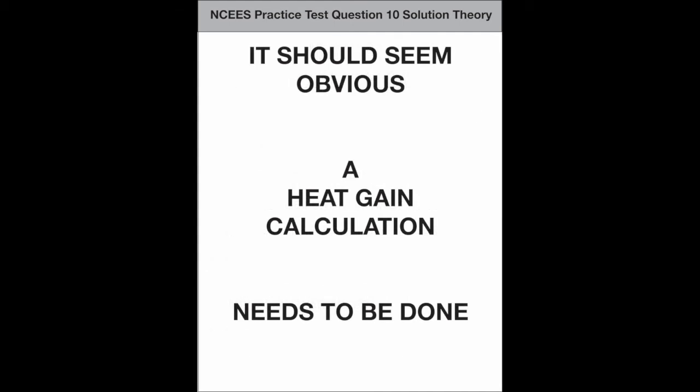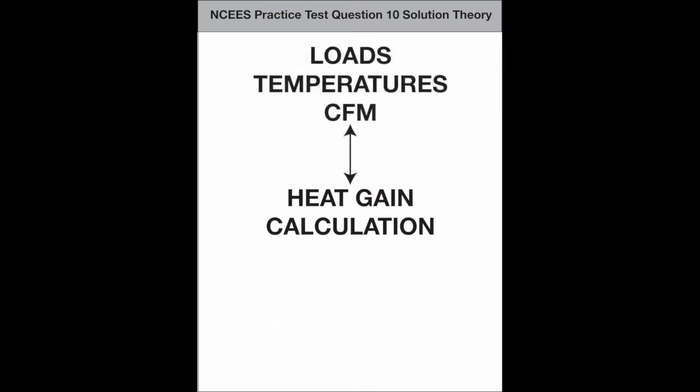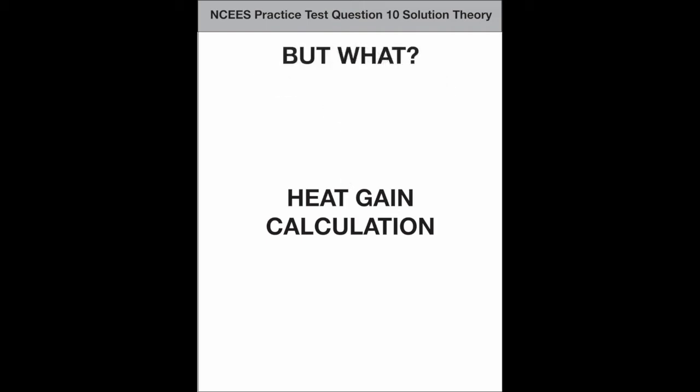It should seem obvious from first reading the question that some sort of heat gain calculation will need to be done. You're given various loads and temperatures and asked to solve for the CFM of airflow. But what heat gain calculation is needed? That's the tricky part.